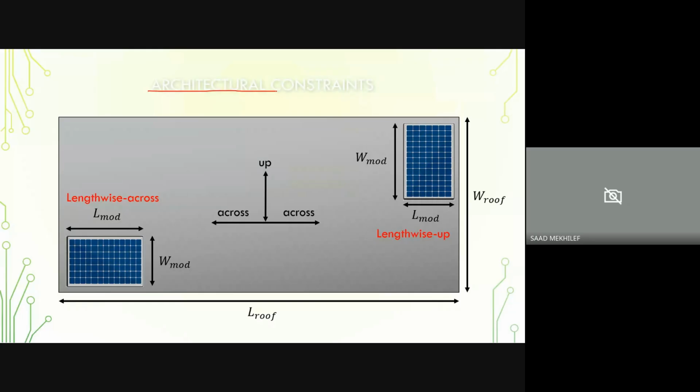Size. So you have the PV panel, and that's why the selection comes in. What types of PV panels should we select? Because you may find 1 square meter gives you 200 watts, and another 1 square meter gives you 500 watts. If you have a space limitation, you should go for the 500 watt. Yes, it is expensive, maybe the price is double, maybe more, but this is necessary. This is to select the right size.